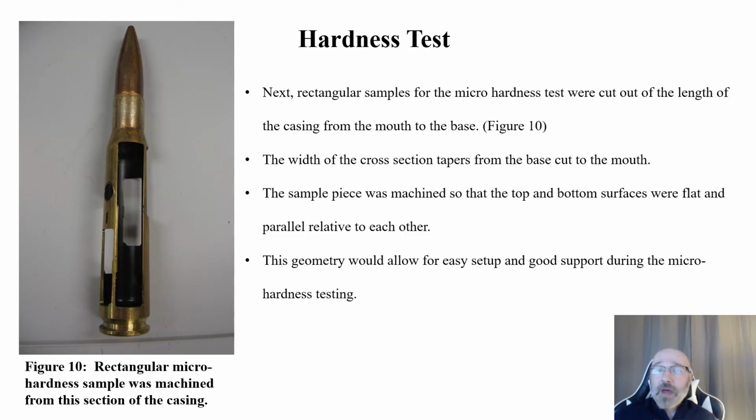Now, if we recall back in this problem here, what we wanted to do was find the mechanical properties of these cases here. So tensile testing was just one method in which we could do that, coming up with those dog bone specimens, putting them in the tensile testing machine, backing out our elastic modulus. Another way that we can do this, and to verify and double check and provide more information on the material properties, is through hardness testing.